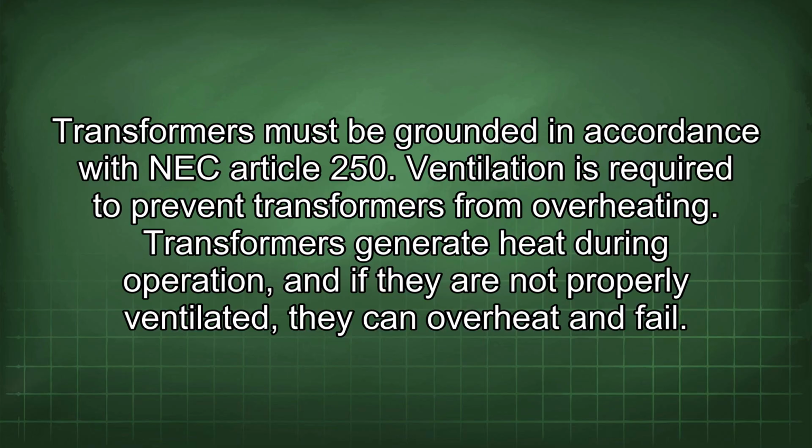Transformers must be grounded in accordance with NEC Article 250. Ventilation is required to prevent transformers from overheating. Transformers generate heat during operation, and if they are not properly ventilated, they can overheat and fail.